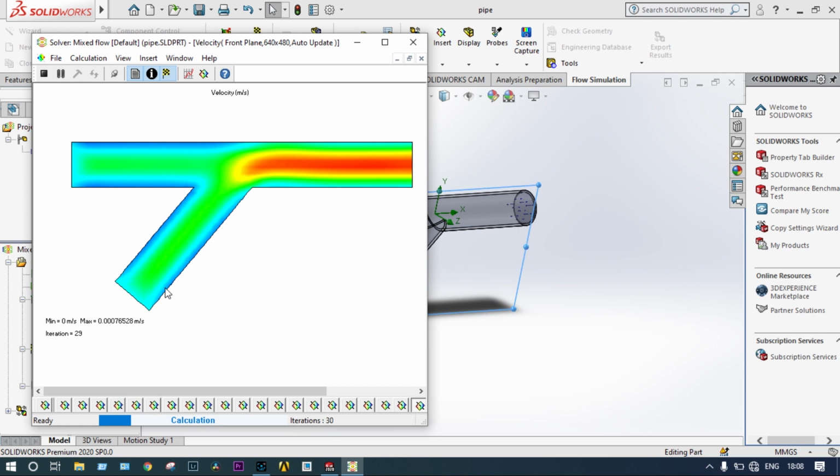Here, also from the velocity profile, at the beginning velocity is normal, but at the junction where two fluids are mixing, the velocity is very high. Another thing we see is that before entering that junction, at the boundary level, velocity is very low, almost zero. In both entry levels, velocity at the boundary is zero. But while mixing, the velocity at the boundary increases again, and maximum velocity is after mixing. So some turbulent flow we can observe here after mixing.